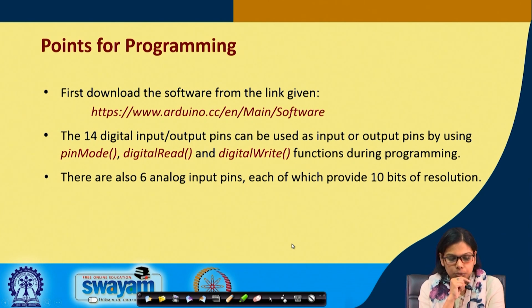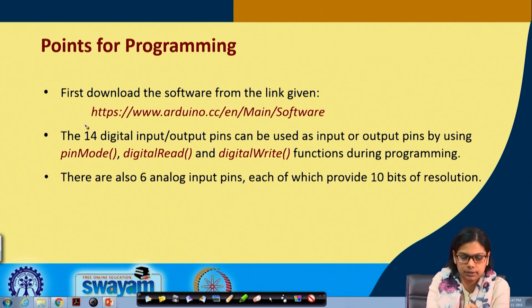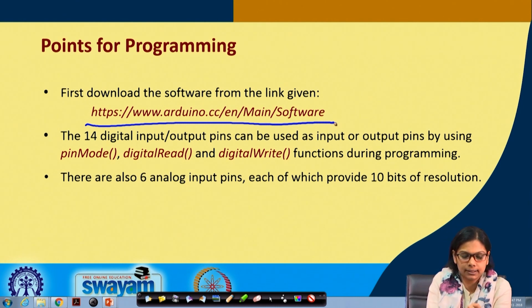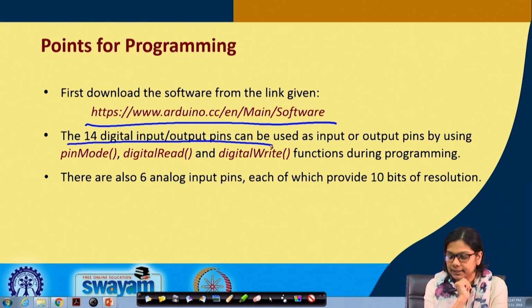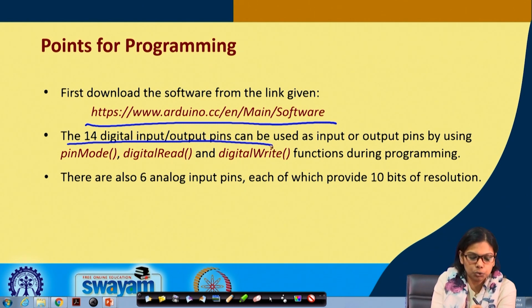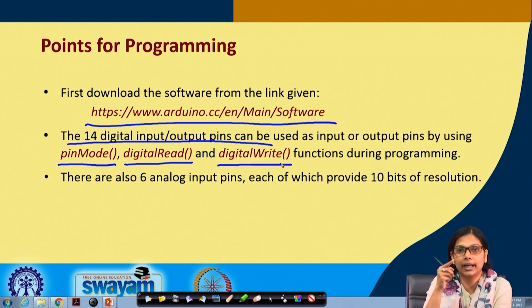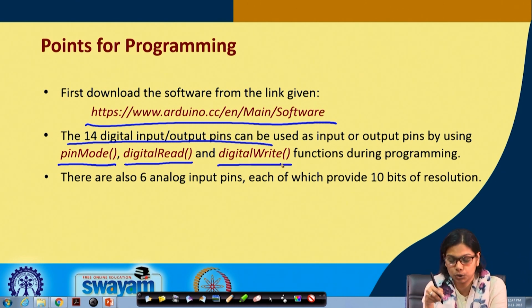So, what are the points that you need to remember for programming using this Arduino? The first and foremost thing is that you need to download the software, the IDE. And for using the 14 digital input output pins, we need to know the following functions. One is pinMode, another is digitalRead for reading the input, and digitalWrite to write the value into the port. So, one is the output, one is the input function during the programming.